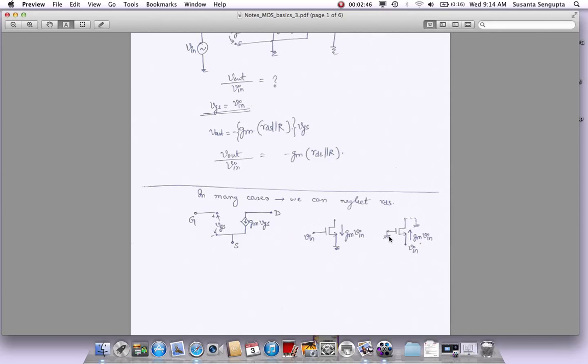We'll look into these amplifiers more, but just to give you the topology, you could have this where the gate is attached to a DC voltage. It is biased to some DC voltage, which is AC ground. Now if I apply the V in to the source, what does it do? Well, VGS now becomes minus V in. This point is ground, this is V in, so VGS becomes minus V in. So in our small signal model, which says GM times VGS, the current goes the other way because it's minus V in. So the current becomes GM times V in. If I apply a voltage here, it will cause a current to go up that way.